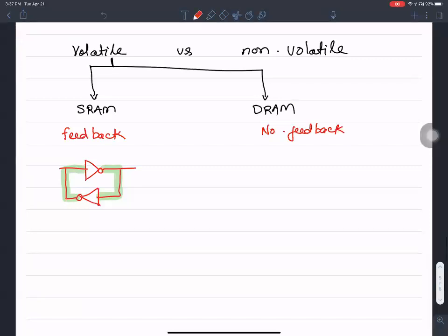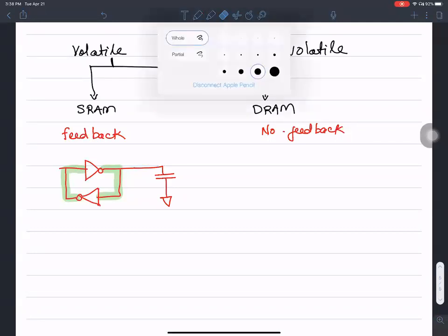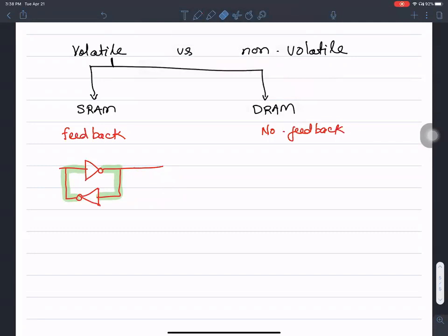Did we come across this idea of a feedback reinforcing, staticizing some of the sequential circuits, the delay, the latches? Yeah, in the latches, thank you. When we were looking at static versus dynamic latch, the dynamic latch had just one capacitance that was driven by an inverter. That was dynamic. But when we incorporated a feedback, a back-to-back connection of inverters, it is a staticized latch. We staticized the latch by incorporating a feedback.